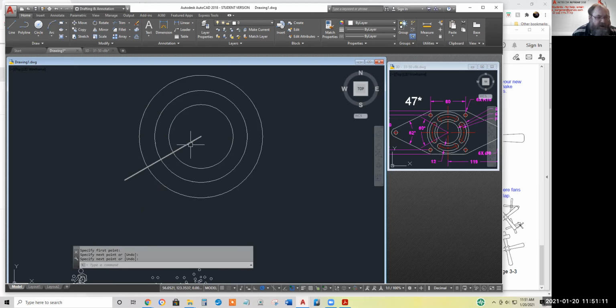Enter. I could copy this on itself and rotate the last item created by a -60, but let me go ahead and simply draw another line about a 30-degree increment. That gives me these two intersection points about which I can draw the circles that'll later become the ends of the jelly bean or the slot.